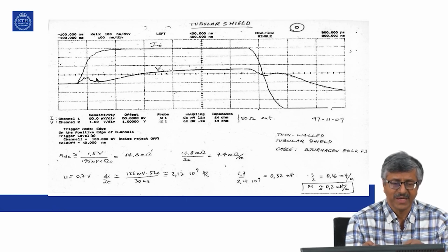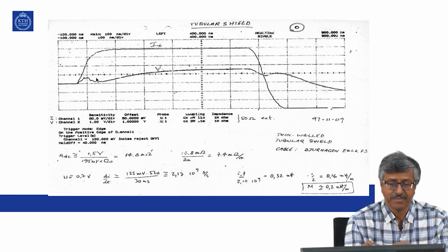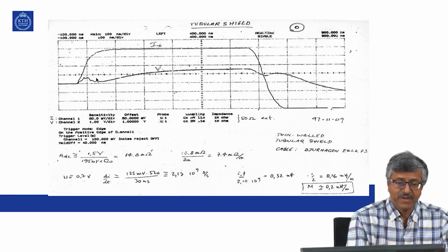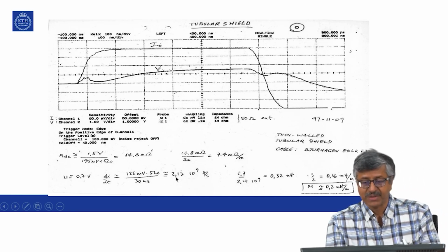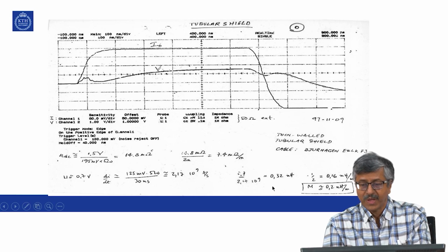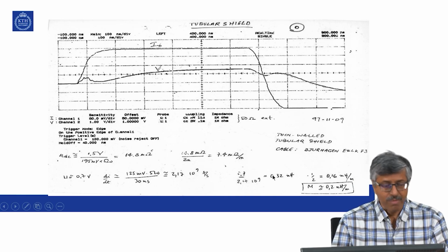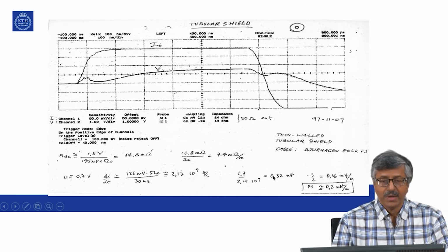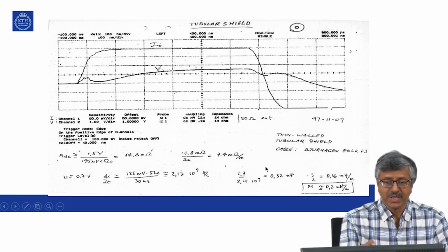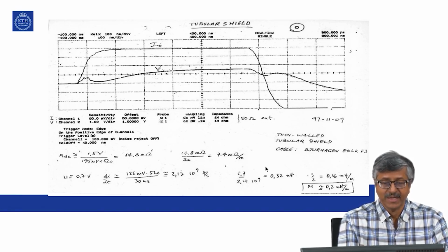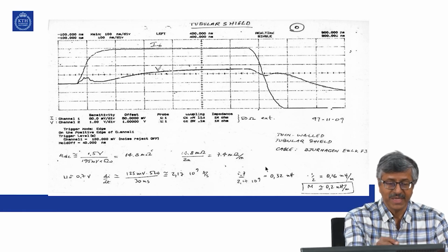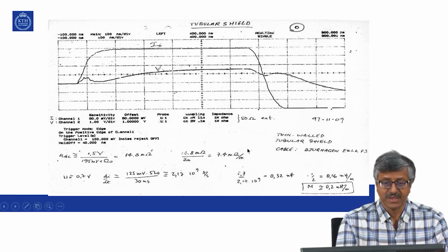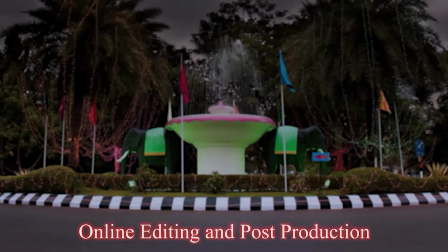It is only a small gap at the edges where the foil is folded over. So, the leakage inductance also is very small, it is 0.32 nanohenry. This shows an illustration of transfer impedance, how to find both the diffusive part as well as the inductive part of the transfer impedance in shielded cables.